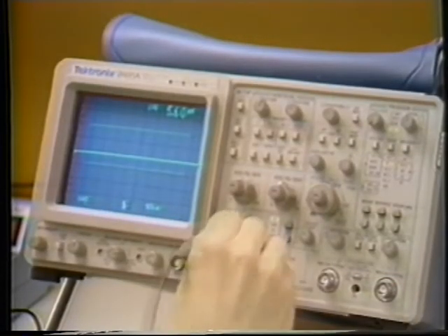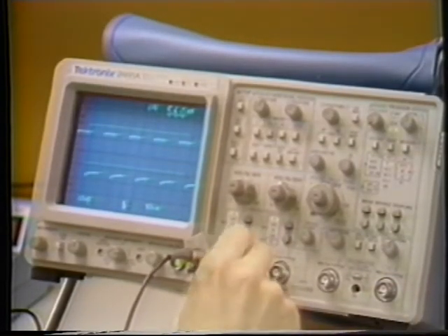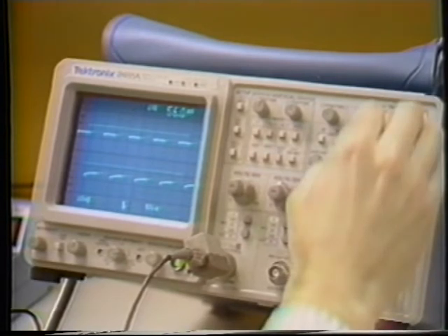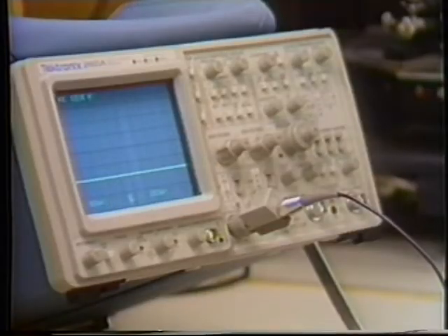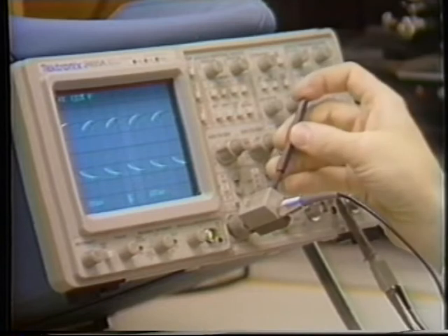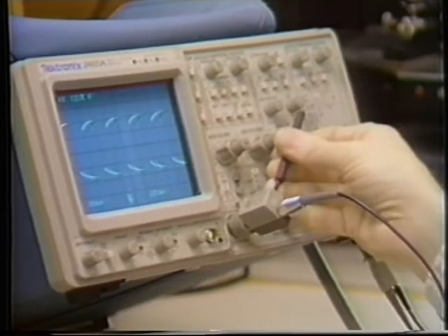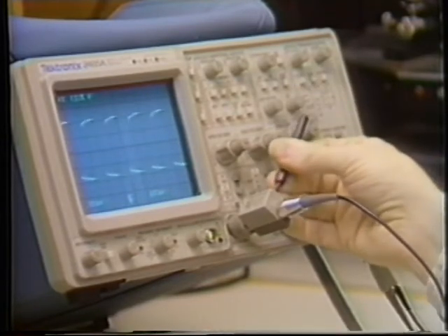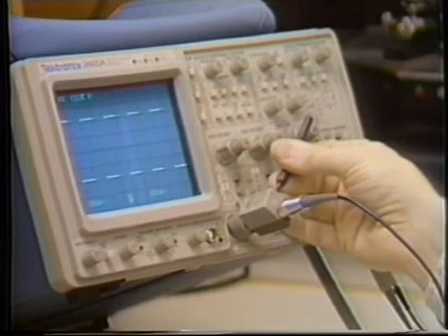What do we do when we compensate a probe? What's so important about tweaking up a square wave? Well, how important is your measurement? Until you make a compensation adjustment, also called low frequency compensation or LF comp, and get a flat square wave response on the calibration signal, you can't be sure that your passive probe forms a compensated voltage divider.